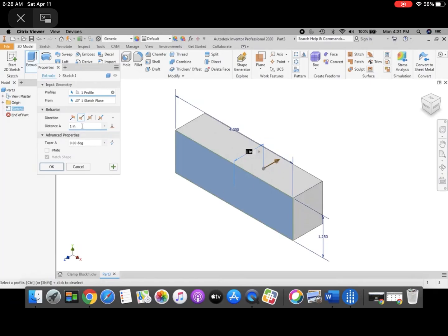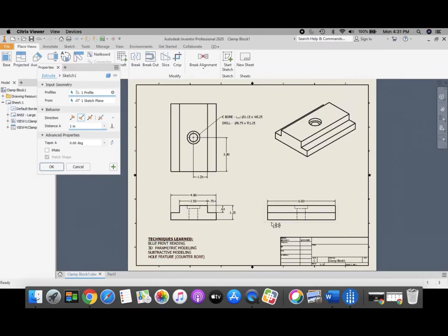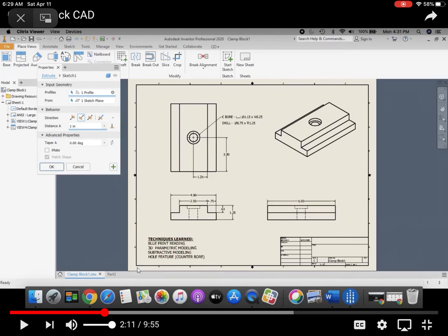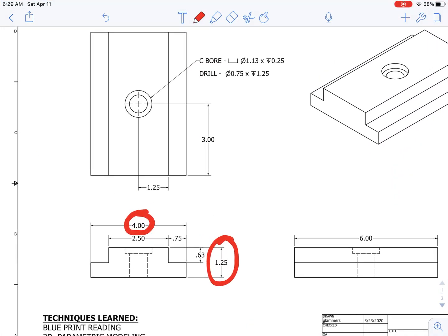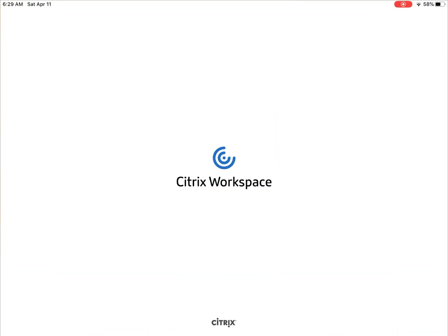how far to extrude. I want to enter in a depth for how far back we're going to extrude. If we take a look at our drawing, okay, I also referenced the dimension in the video as well. Extruded 6 inches. Okay, 6 inches. So now I can go back. I can reference that from my drawing as well. 6 inches is right here.